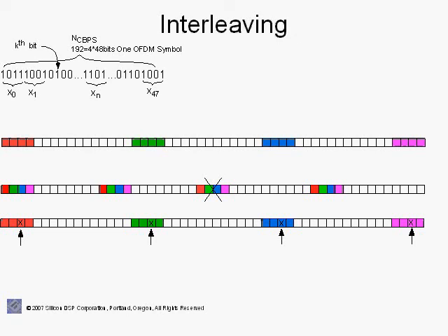Interleaving and deinterleaving combined with forward error correction coding is very important in terms of preventing bursty errors when you have deep fades in which multiple carriers can be wiped out or are received with low SNR and you have low reliability in the bits. Without interleaving, bursty errors might happen.